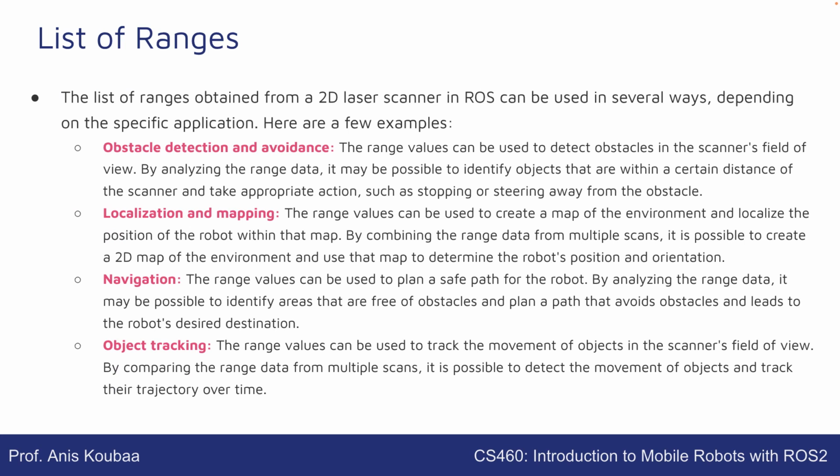Okay, so the list of ranges can be used in different ways. First of all, in a 2D laser scanner to detect obstacles and avoid them, and also to do localization and mapping. This is something that we are going to explore further with the navigation.